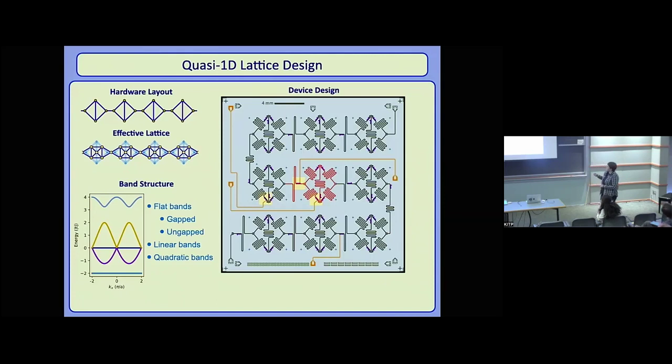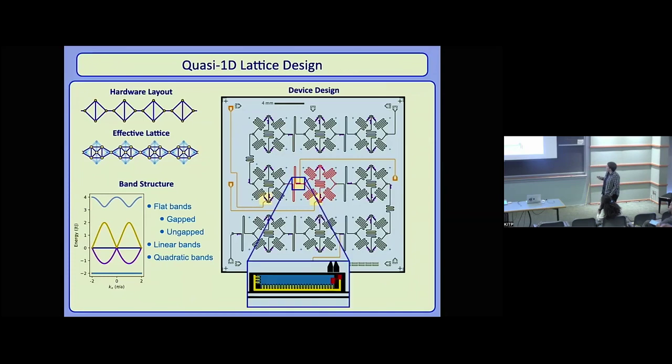And so to keep that from detuning these 3 sites that actually have the qubits in them, we've written the capacitor portion of the transmon in every resonator, but only added the Josephson junction in these 3 locations. That keeps the disorder relatively low while giving us these 3 tunable emitters inside the lattice that we can bring into contact with the various energy bands. So that's the CAD. And this is the transmon again that's embedded right there.